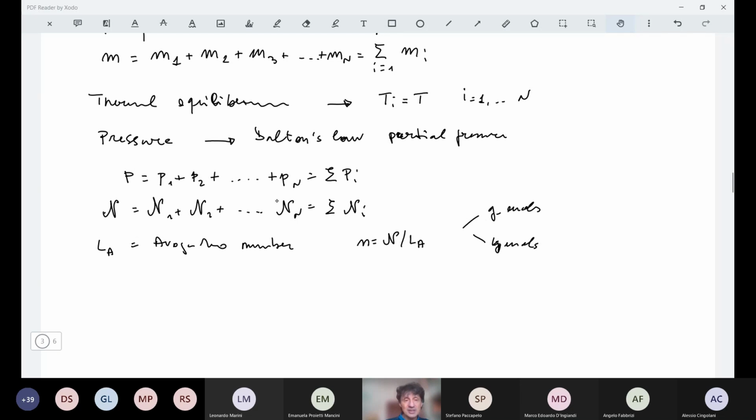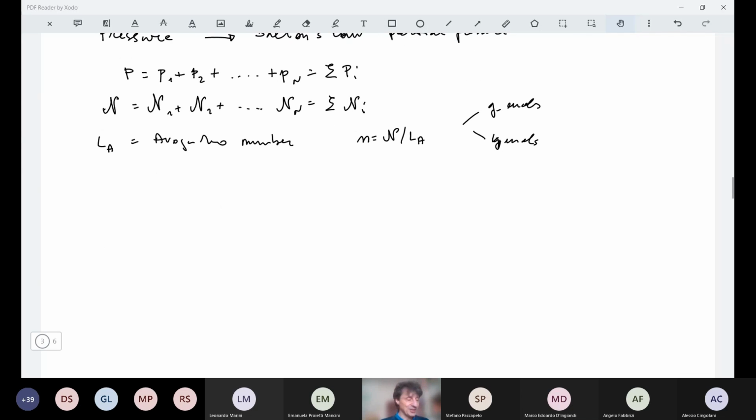So with this, the last step is to recall that we are considering perfect gases, and so for each of the species there will be the perfect gas equation P equal to nRT with the universal gas constant, and if I sum over i, sum of PiV equals sum of niRT, it means sum Pi is P, and so sum ni is n, and so the same relation is also valid for the mixture.